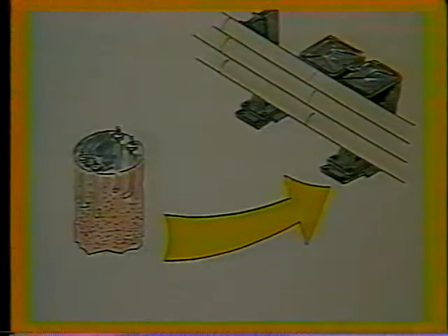4 basic anchoring alternatives are suggested by the manufacturer for the system. The first option involves driving a wooden post with a platform attached to the top of the post. The second option uses steel I-beam driven into the ground to anchor the unit. The third option calls for embedding L-bolts attached to the slip bases in 4,000 psi concrete footings. The final alternative uses expansion-type or flush-type anchor bolts to fasten the Sentre to a 4,000 psi minimum concrete pad.